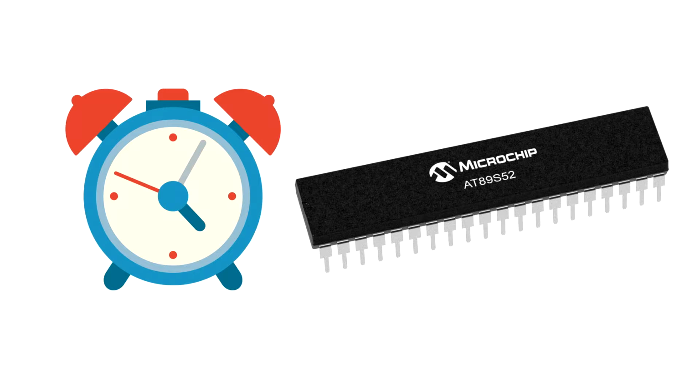Let's make better delay functions with the hardware timer. The timer and counter is a peripheral built into the 8051 used to time events, create delays, generate baud rates, as well as count external events. The 8051 has two independent timers, timer 0 and timer 1, which are 16-bit wide.